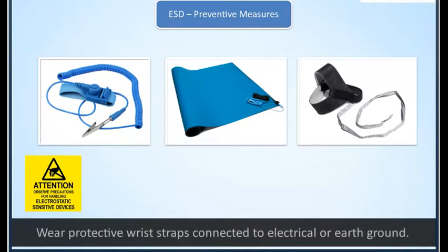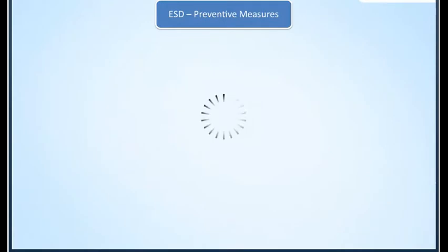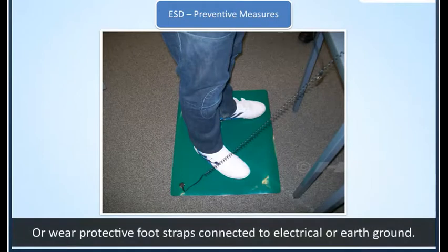Wear protective wrist straps connected to electrical or earth ground. If wrist straps are not possible, then wear foot straps connected to electrical or earth ground.